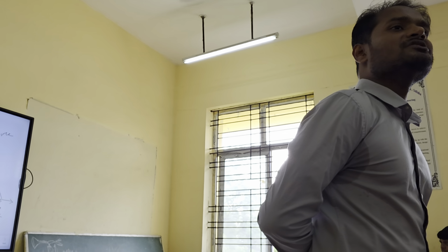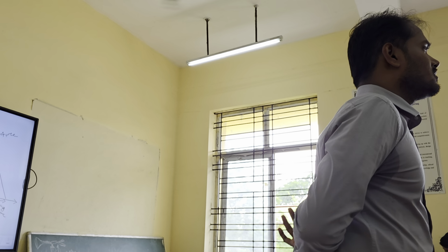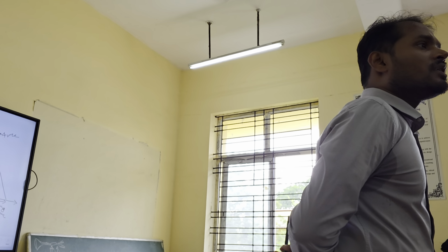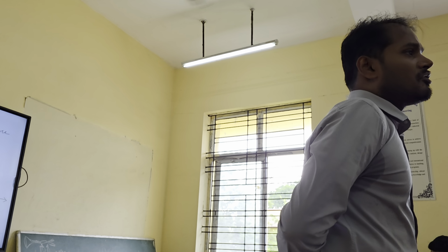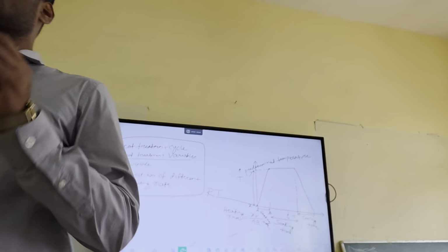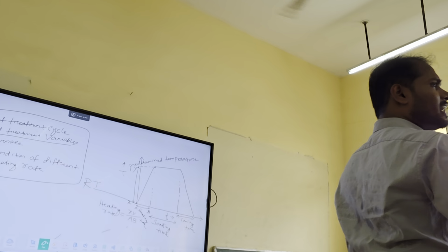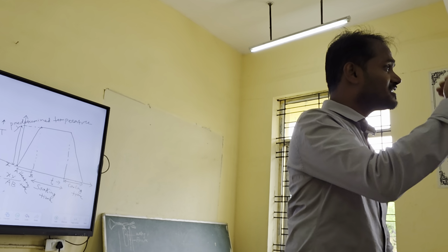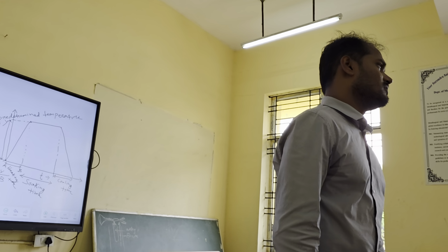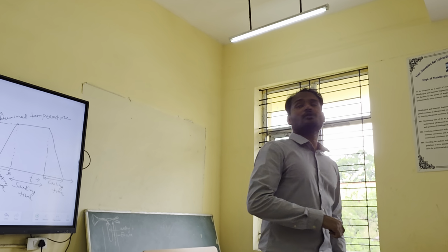Can you check how much temperature you can go in Super Kanthal and how much in Kanthal? That is the limit. Okay, 1800. Yeah. So if you want to go to very high temperature, you can use Super Kanthal as a heating element. That will provide you heat energy. But if you want to go to 1400 or so, then Kanthal is fine. You cannot use Kanthal for high temperature, otherwise it will melt, or get oxidized. It is fine after this. Okay.